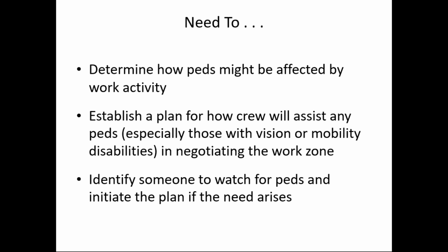And remember that someone you identify should not be the flagger. Flaggers, in my opinion, have enough to do. They shouldn't be also given this responsibility. So it should be someone other than a flagger who also, depending on what they're doing, should have the ability to watch for pedestrians and initiate the plan.